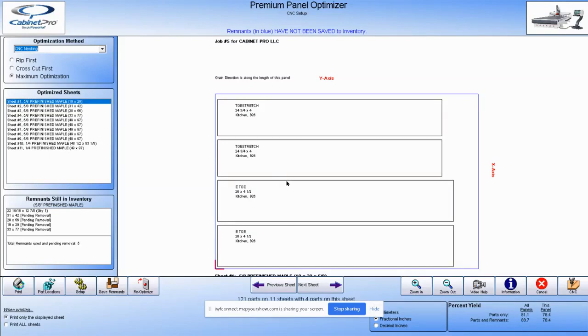That spacing is the diameter of the tool that is going to be used for the cutout of these parts on the CNC router. And by the way, every single material can have a different tool cutting out the parts on that particular material, so it happens automatically. Once you set it up, you don't have to worry about it anymore.